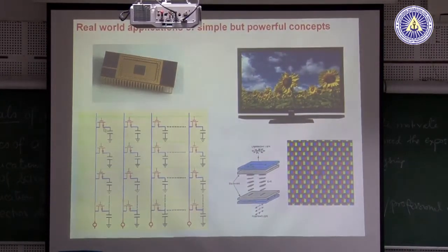And if I want to understand this 1-bit memory cell, it is called a dynamic RAM because it has to be refreshed. If you don't refresh it, the capacitor loses its charge. These transistors are not perfect transistors, they leak charge. So you have to refresh it.